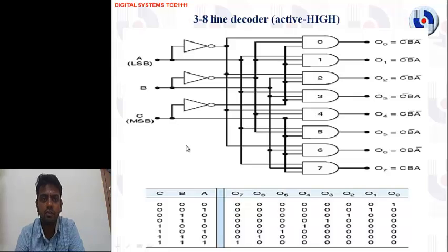As per requirement, if we are considering 3 inputs from the application, then we can use a 3 to 8 line decoder, which is constructed as shown in the diagram. These A, B and C are the inputs and these are given to the 8 AND gates. These 8 AND gates have 3 inputs, A, B, C, and 3 NOR gates are also used to generate various combinations.